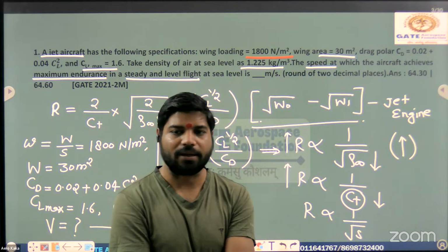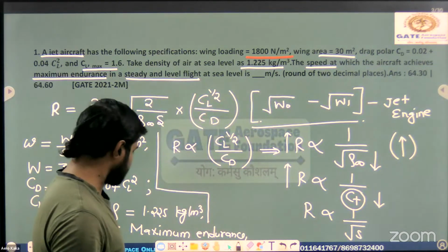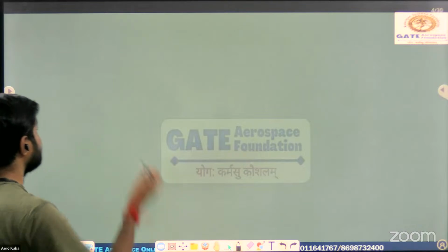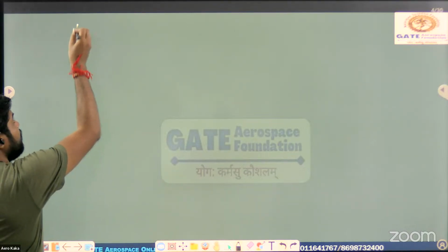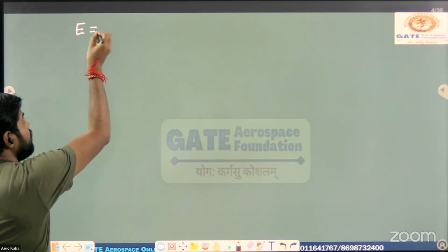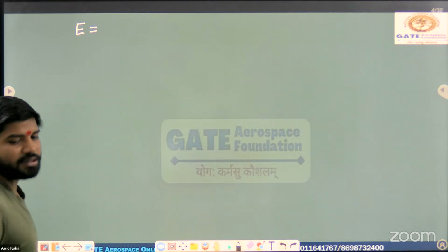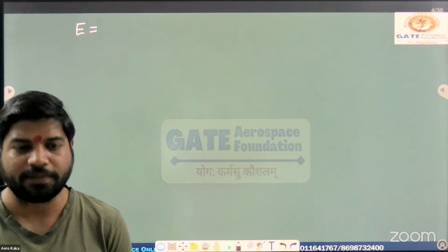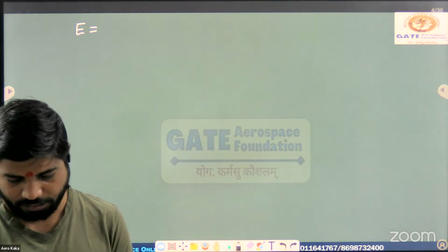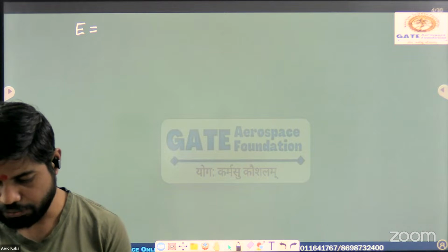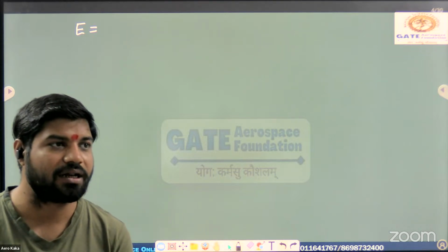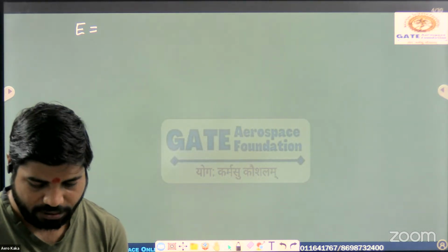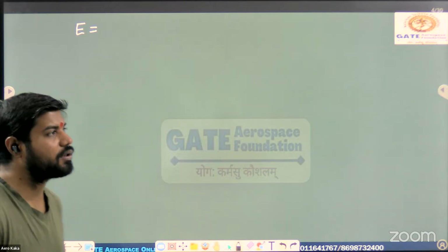Okay. Now here let's write down our endurance formula. E is equal to, what is the formula? Capital E is equal to 1 upon CT into CL upon CD, or the L by D ratio, into ln of W naught upon W1, right?